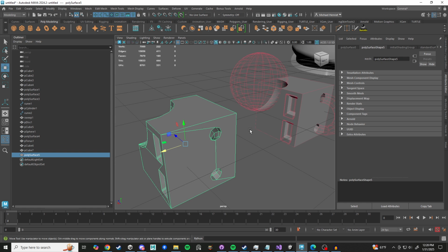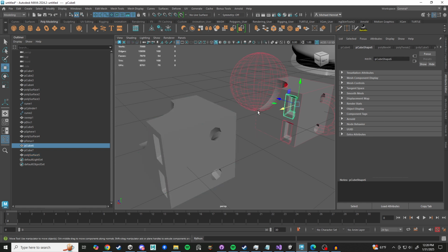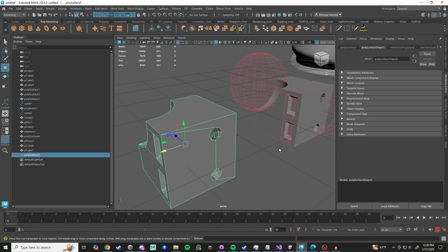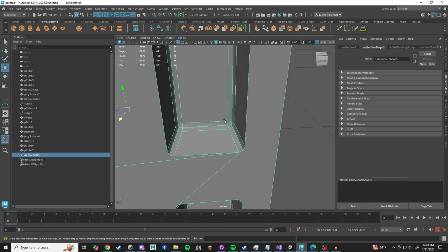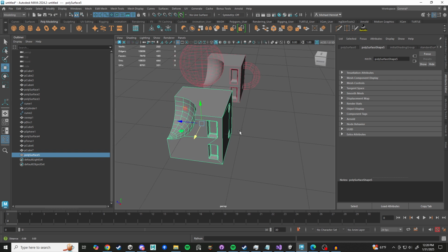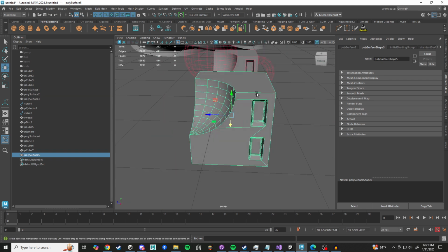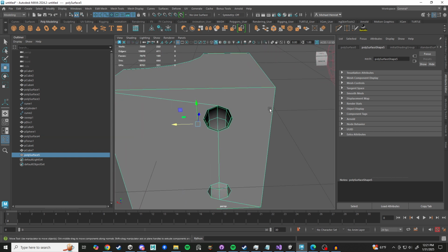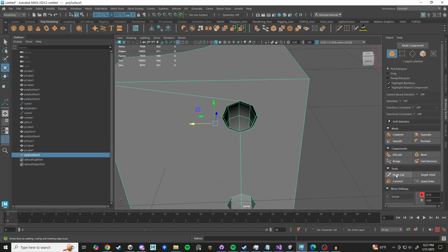one, this gets rid of the history on it, so it's easier for Maya to calculate things with it. But also, if you leave it there, by duplicating it out, you leave the one that you were working on. So if you have to make any modifications to these shapes, or change the cut parameters, anything like that, you still can do that and then just duplicate it out and move it over, you know. But if you're very satisfied with your Booleans, you've got to start resolving these edges, right?